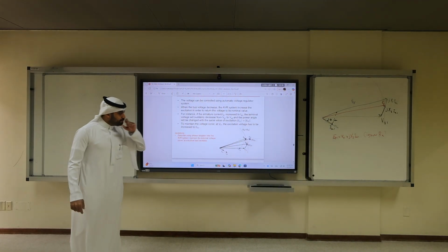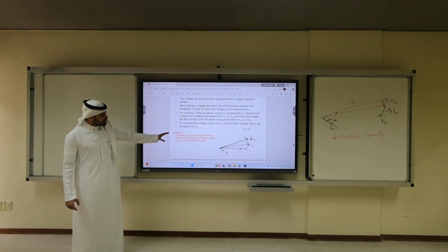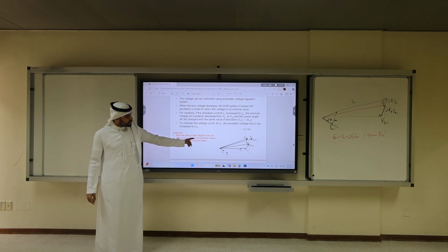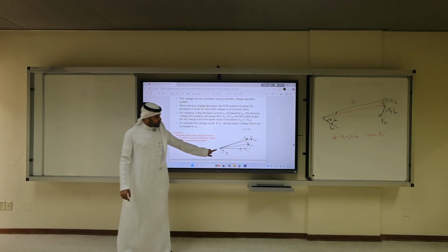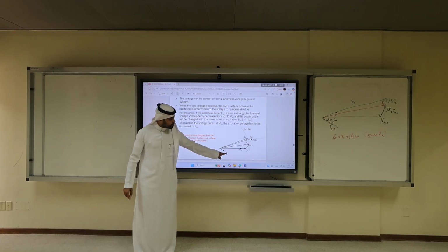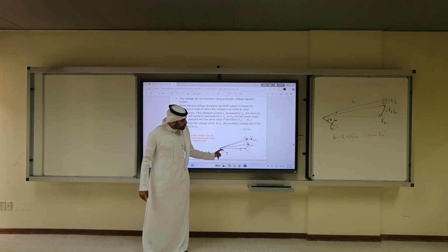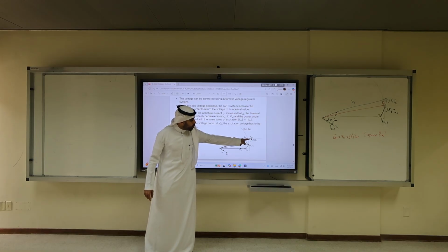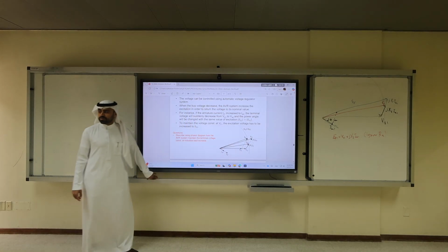So in the exam, we'll ask you questions like the ones in red. Describe using a phasor diagram how the AVR system maintains the terminal voltage at inductive load increase. So if we increase IA2, we either have to reduce VT2 to get constant EF2, or we have to maintain VT1 and get another EF3 longer than EF2 and EF1. You cannot have them both in life, okay?